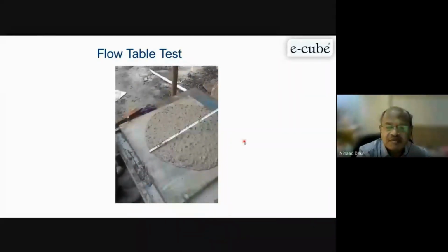Today we must have heard about these columns, whatever we have seen, metro or any other project. The whole column may be about 6 to 8 meters in height. We are casting in one go. We cannot use slump concrete. We have to use only flowable concrete.